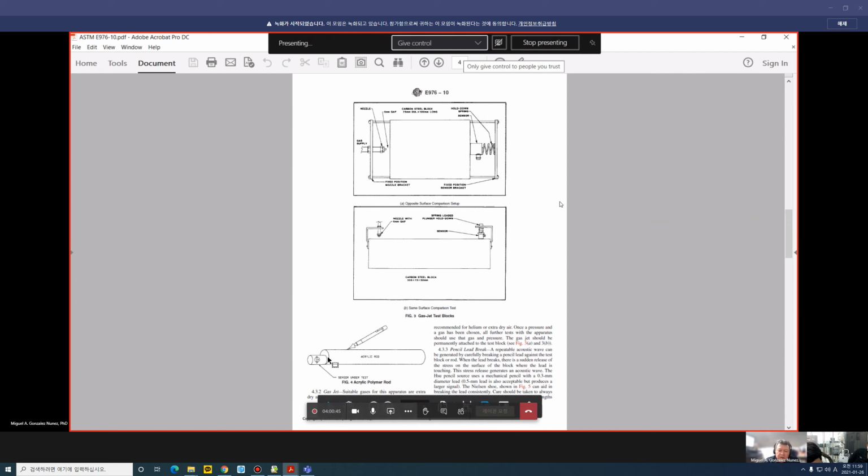For this one, you use high vacuum silicon grease to mount the sensor, and you can use that for comparison in your test specimen when you don't use any couplant, when you use just the dry coupling, and when you use the membrane.